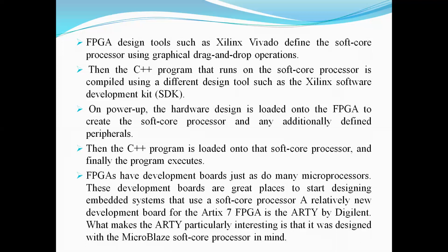Now, FPGAs have development boards just as many microprocessors do. These development boards are a great place to start designing systems that use a soft core processor. A relatively new development board for the 7 series FPGA is the Arty by Digilent. What makes the Arty interesting is that it was designed with the MicroBlaze soft core processor in mind.